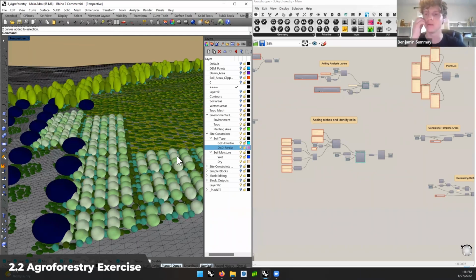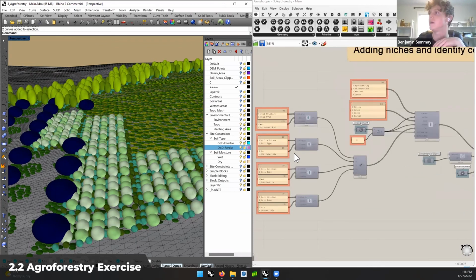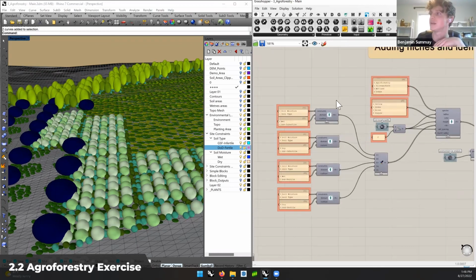to spread out, are being filtered through in maybe a CSV or in the Grasshopper script like we're doing here. We could have just as easily created a CSV file that outlines what the different modules are, and then feed the CSV in here, and it just reads a CSV of the different types of information that we're working with. And then you can add and subtract from that CSV to change how the script is being